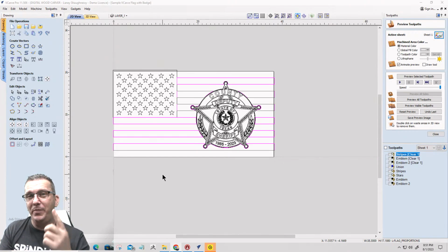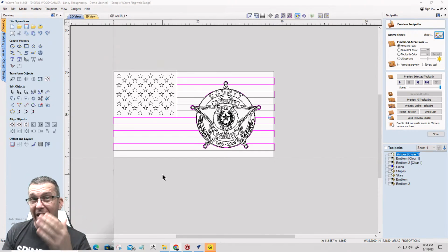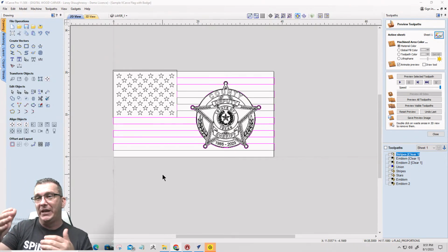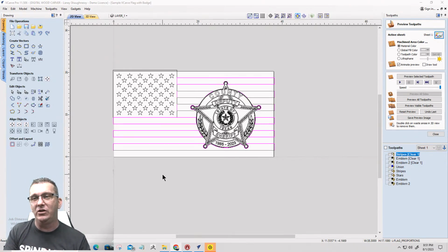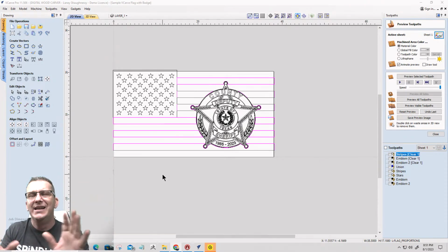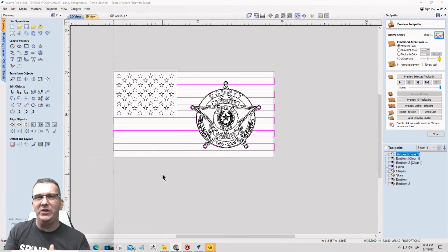So on that high pitch, you need to go faster. I'm telling you, go faster. And you need to turn your RPMs down. That needs to spin slower. Your speed needs to be slower, and you need to be moving faster. You find that happy medium. If you turn yourself down to 18,000 RPMs, and you were traveling, let's say, 60 inches a minute, and you get a high pitch whine, go up to 70, 75, go a little faster.